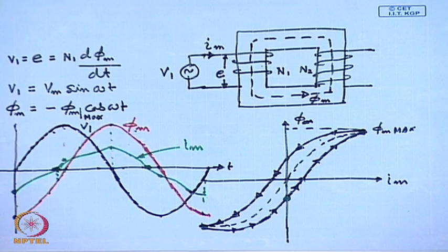The current responsible for eddy current loss will be drawn from the supply, and it will be sinusoidal because the currents induced due to flux variation in the core are sinusoidal. So, to compensate for that, sinusoidal current will be drawn. So, another small sinusoidal component in phase with the voltage will be drawn to supply the eddy current losses. These two components will constitute the total no load current I 0.